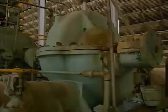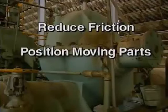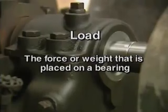Bearings are found in almost every type of moving machinery, and they perform three basic functions. They reduce friction, they position moving machine parts, and they carry load. The term load refers to the force or weight that is placed on a bearing. Different bearings are designed to withstand different types of loads.